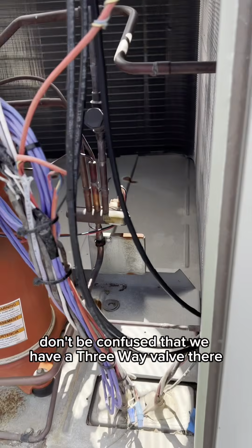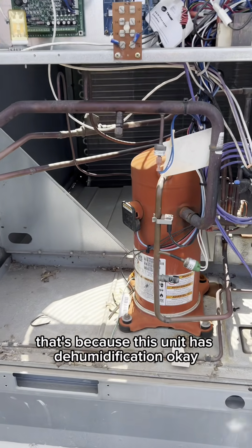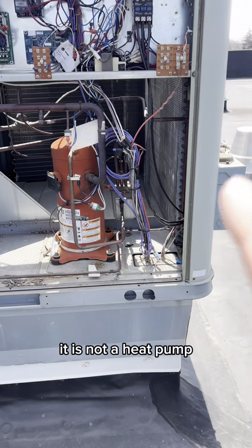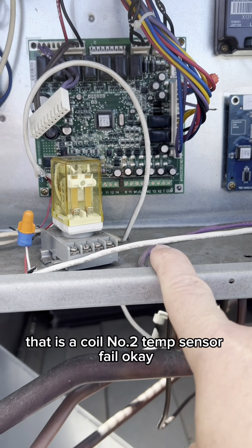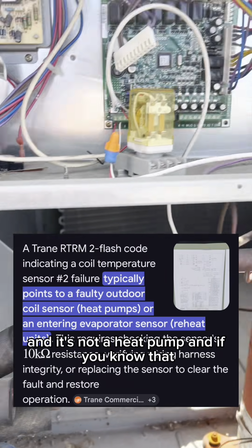Now, don't be confused that we have a three-way valve there. That's because this unit has dehumidification. Okay, there's a reheat coil in here that allows this unit to go into dehumidification. Okay, it is not a heat pump. But I'm getting a diagnostic on this RTRM board that is a coil number 2 temp sensor fail. Okay, there is no coil 2 temp sensor, and it's not a heat pump.